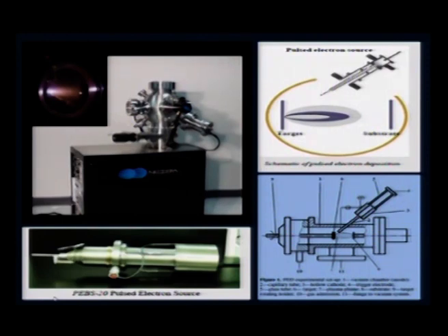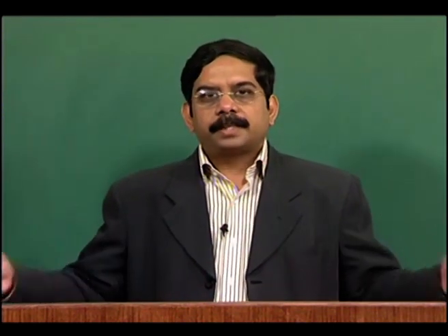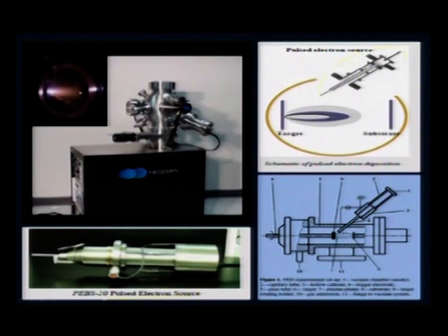As you would see here, this is the dimension of a PED, and what is important in this deposition technique is the pulsed electron source, which is called the PEPS source, and this is the core of the PED technique, where the pulse electron beam comes from. But for that, the vacuum chamber and all the energetics are nearly the same as a PLD. So what you do, you avoid the complex problem of maintaining a gas source for laser, and then the cooling systems plus the optics to guide the laser light into the vacuum chamber. All these are avoided by just using a pulsed electron source.